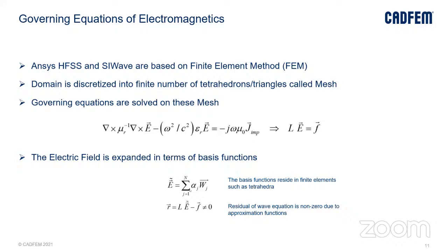The finite element method is basically dividing the structure into a finite number of tetrahedrons in case of volumetric structures, and triangles in case of planar or surface structures. This we call the mesh.